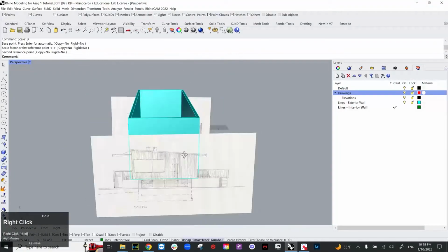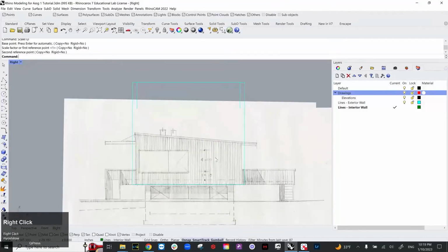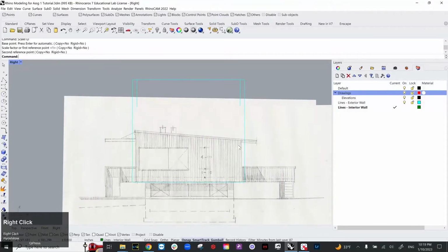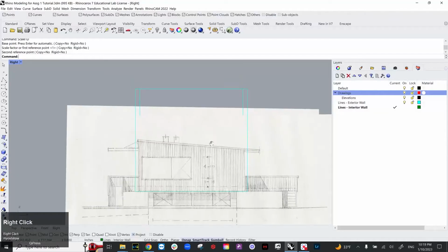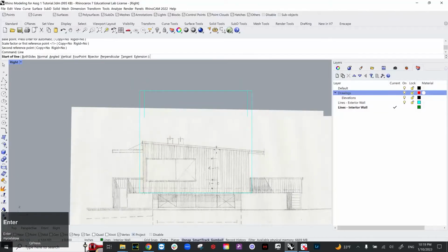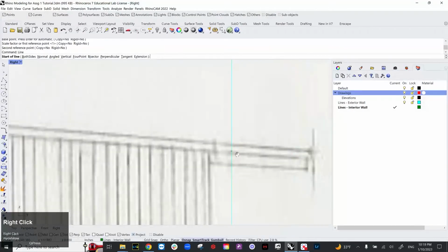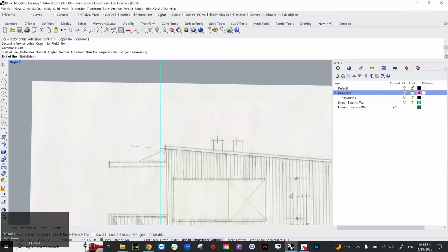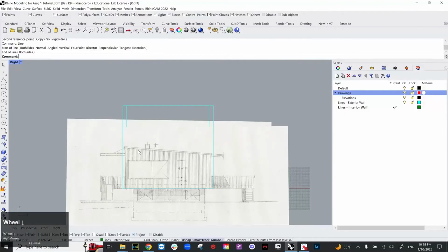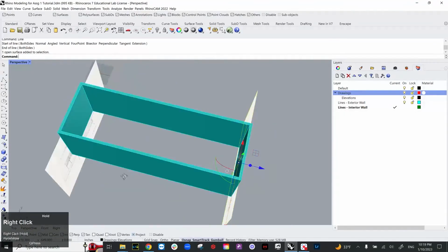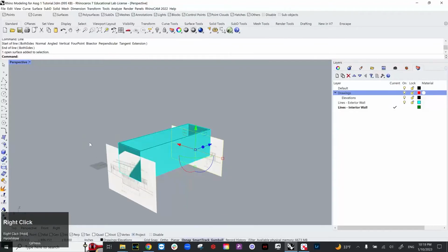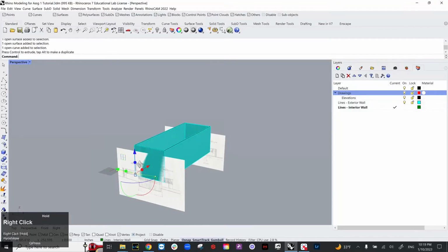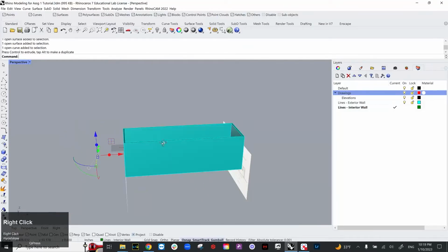And then on the right, I'm gonna press project, check the project over here. I'm gonna draw a line over here, and I'm just gonna draw a line over here, like this. And wherever the line went, over here, I'm going to use this line to cut this geometry in the angle.